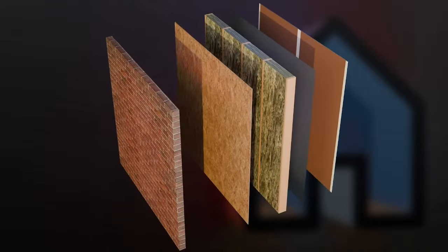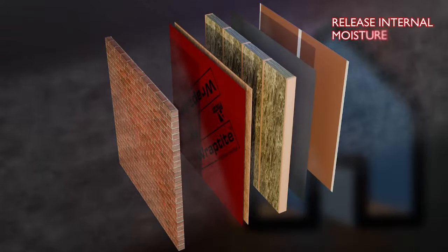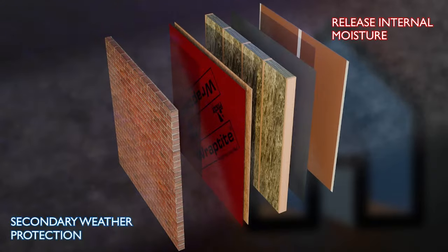Positioned on the outside of the structure, vapor permeable membranes allow the building to release moisture whilst providing secondary protection against the weather, helping make the building structure wind and watertight as soon as possible. This not only reduces the amount of moisture that must dry out post-completion, but it may allow for interior fitting out to begin earlier by helping to provide a warmer and drier working environment.